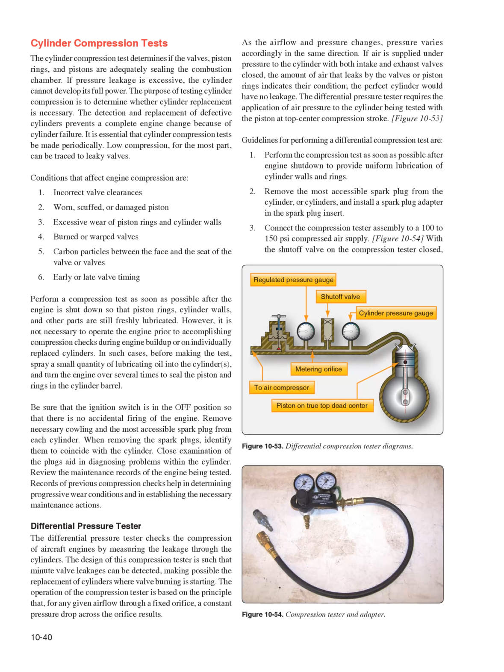Cylinder compression test. The cylinder compression test determines if the valves, piston rings, and pistons are adequately sealing the combustion chamber. If pressure leakage is excessive, the cylinder cannot develop its full power. The purpose of testing cylinder compression is to determine whether cylinder replacement is necessary. The detection and replacement of defective cylinders prevents a complete engine change because of cylinder failure. It is essential that cylinder compression tests be made periodically.